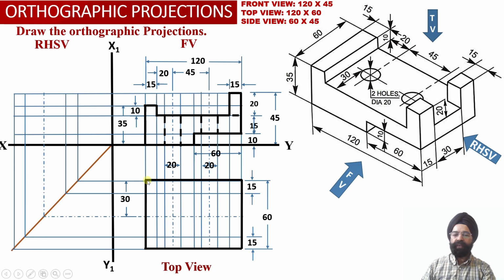Now as the observer is going to look at the solid from the top, the boundary of the solid will be visible to the observer from the top view projections, because at all points, even though the cross section heights may be different, there is continuity in the surface maintained on either side of this particular cross section.